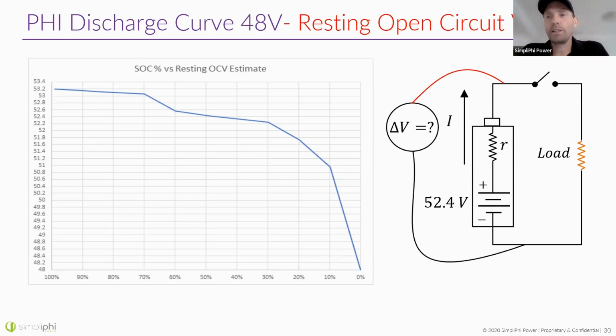What happens as you get really low temperatures is that in the salt solution, the ions are moving very slowly. And because those ions are moving very slowly, you have high internal resistance. And so you have to apply a high voltage in order to get those ions to move quickly. So those limitations are based on the mobility of the lithium ions at very low temperatures.